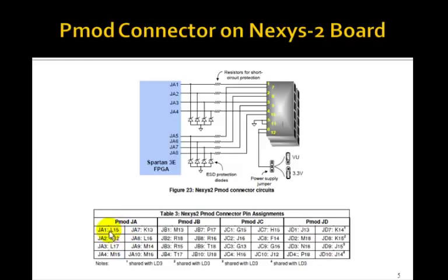So you would have to modify your UCF file to give the names, say direction and PWM, and associate direction with pin L15 and PWM with pin K12. There's a jumper here. Normally you would put this jumper to 3.3 volts, which is what the H-bridge circuit would normally run at.